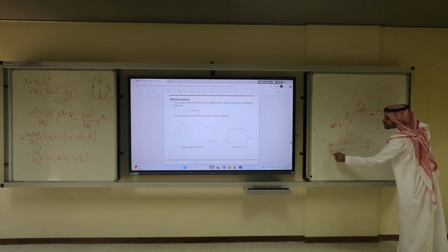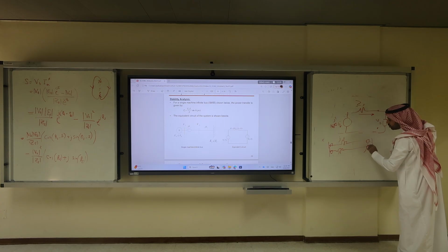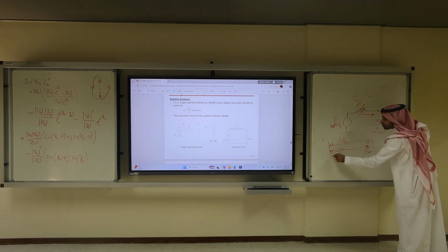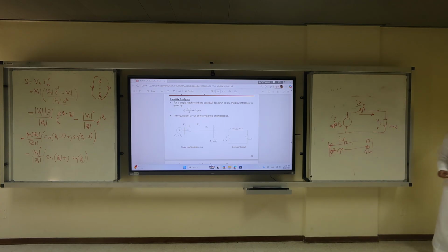If you have these two breakers now closed, you have equivalent impedance of 2.5. So you can control it by controlling which lines are connected to my generator. So you as a generator, the more lines are closing their breakers to you, you should estimate the impedance, and based on that you calculate your power.